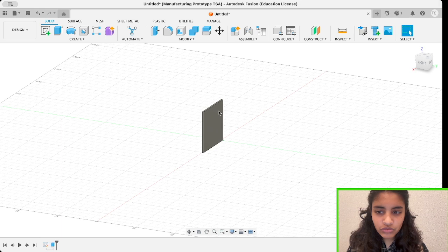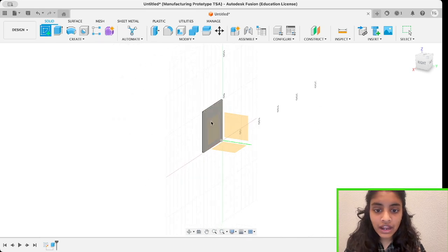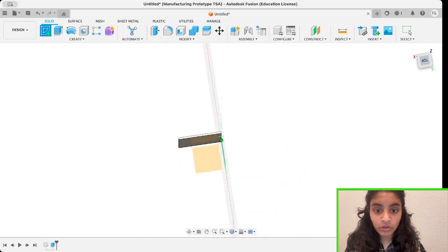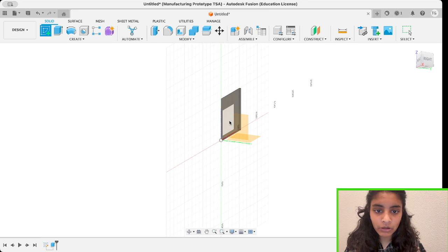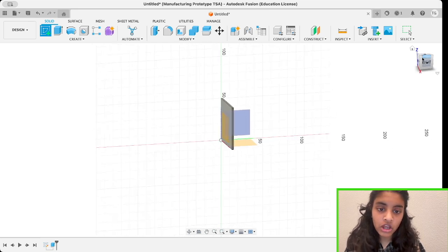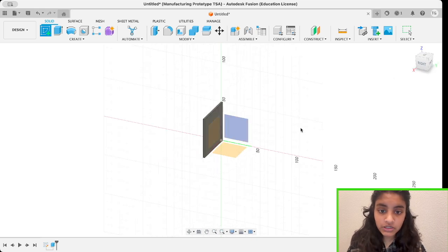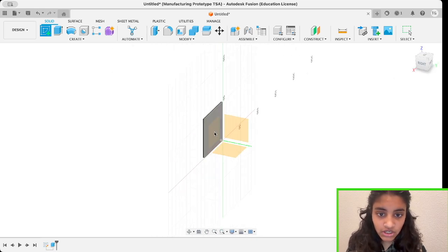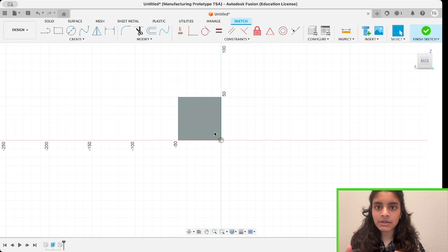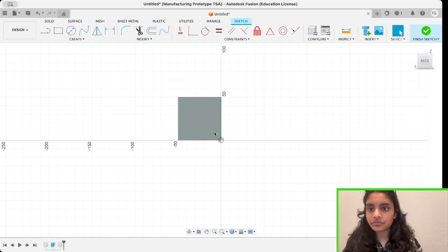To add a new component or a new part to this basic body that we have here, we're going to click Sketch again. Now this sketch is going to be determined based off of this base project we already have. If we want to build on the back face of this block, or on the front face, I'm going to choose this front face of the block and use it as my sketching plane. So now that becomes the base of our new sketches.